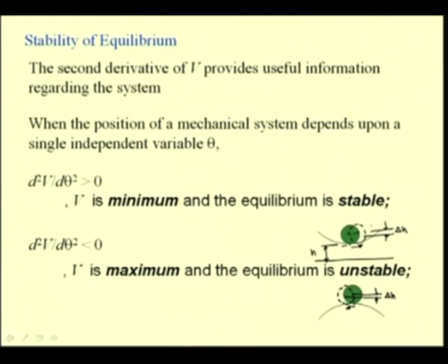So, potential energy rises when there is a small disturbance, and the system always tries to come back to the least potential energy configuration. So, again it came to the original position. So, we said that the equilibrium is stable, but if we see in this case, for the displaced position given by these dotted lines, the change in its mass center reduces the potential energy for this new configuration.